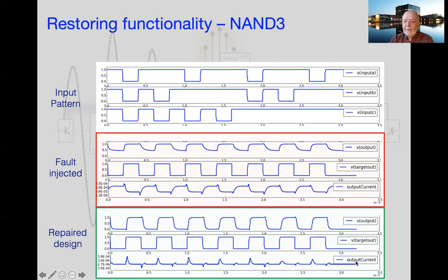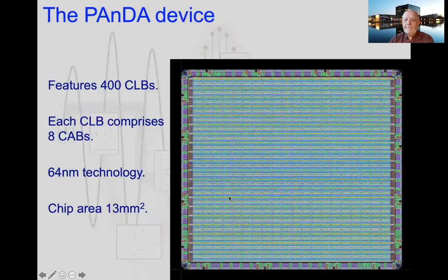And you'll see that the average output current has reduced significantly compared to here. If you look on the scale, we're talking about 10 to the minus 6, whereas up here it was 10 to the minus 4, 10 to the minus 5. So the output current is reduced, and we just get pulses when the circuit is actually changing, which is what you'd expect. But the average current level has come down nicely, and the functionality of the circuit is working rather well. So that shows that not only pictorially, but also functionally, the circuit worked nicely.